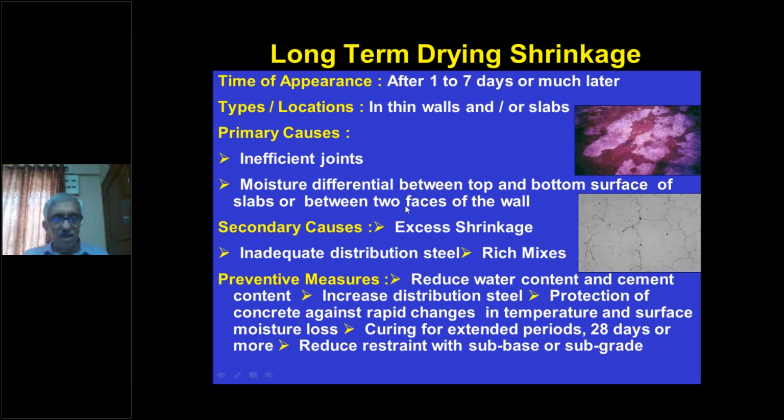So nowadays we do not specify proper mechanical joint between the base of the slab and the pavement concrete on the top. So we put either a sisal craft paper or a plastic sheet and then put the pavement concrete over it.